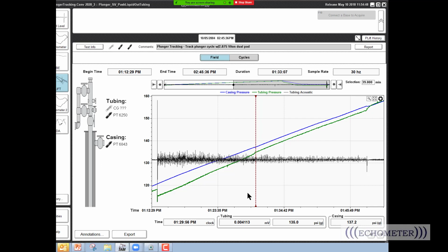And so if you have a salt block, it reduces the area that you have in the casing. It provides less energy to bring the plunger up, and the casing pressure doesn't change because it's blocked. It's trapped. Now you can shoot a fluid level down the casing and release the plunger from the bottom.